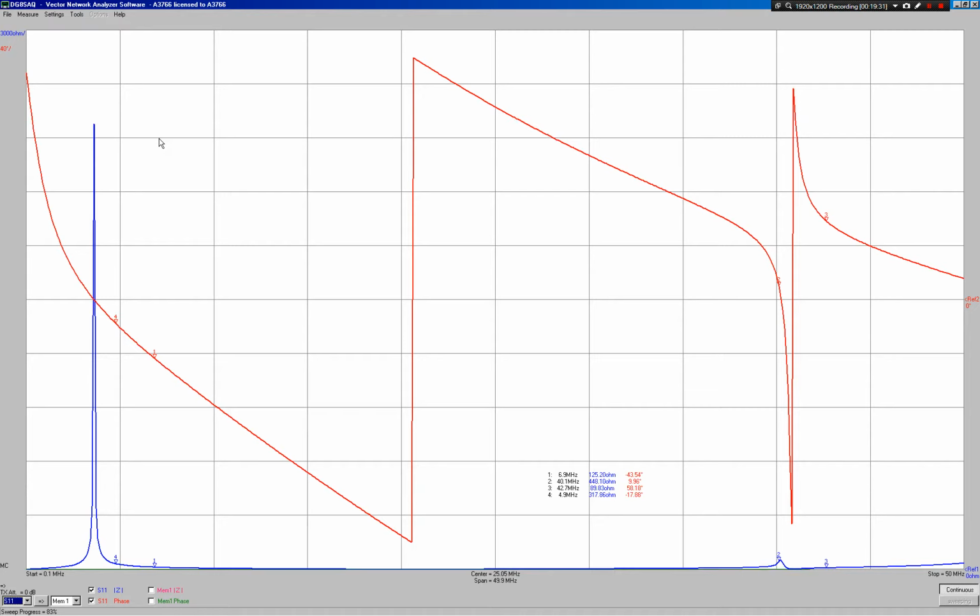It applies to the flat coil, it applies to the cylindrical coil. Actually, all Tesla coils in this kind of geometry, with a primary and a secondary with a non-zero coupling up to about half, will display that same kind of characteristic as the primary resonance circuit and the secondary resonance circuit interact.